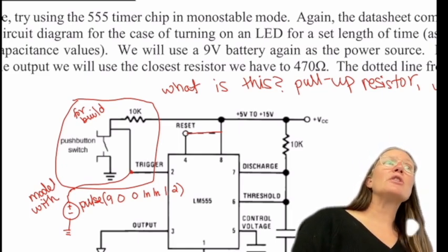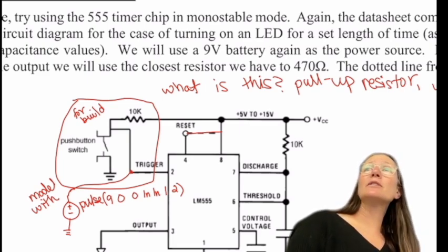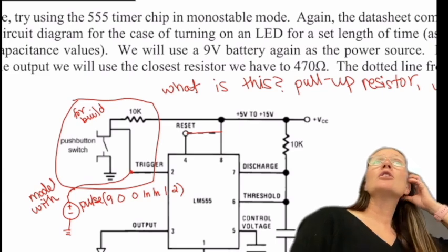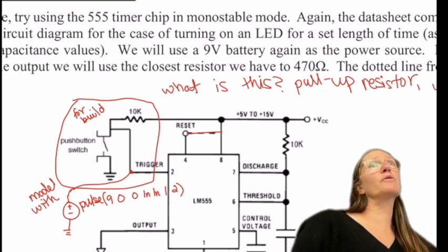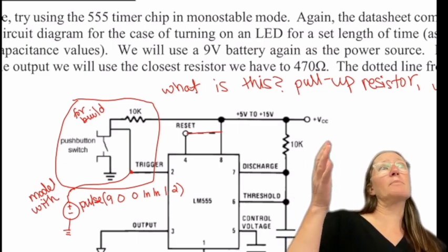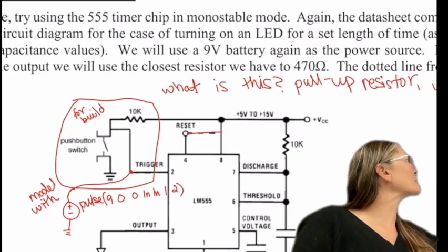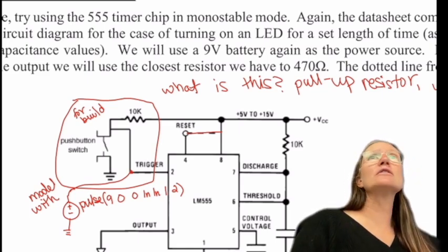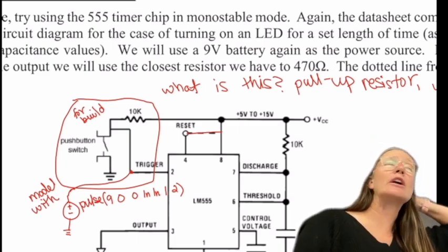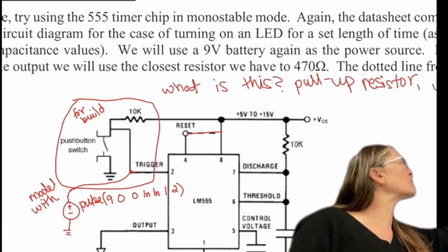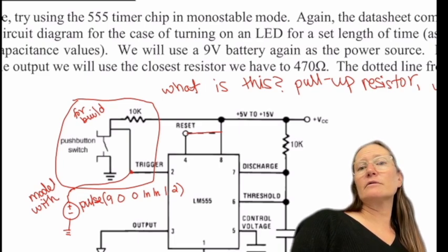There are some SPICE directives, where I have that .tran, that means I want to run a transient. You can do a .meas, which is going to do a measuring. So if you want to do power consumption in elements, I will put together a little sheet with the syntax that will be easier for you guys to look at, and then you run them at the same time as this.